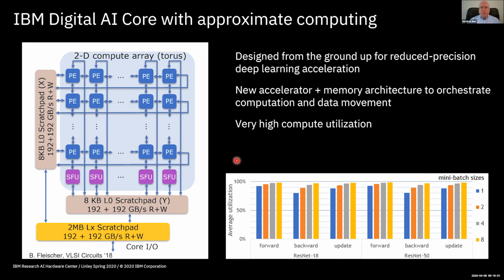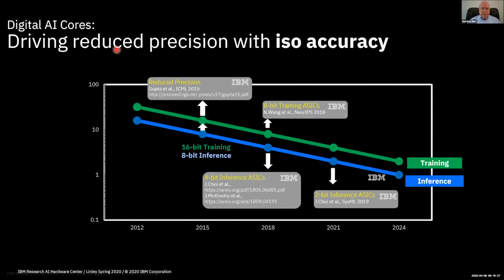It turns out, the approach my colleagues have taken is that by the point you get to 4-bit or 2-bit activations and weights, it actually is more costly to use sparsity unless you could guarantee you're going to be at 90%, 80% sparsity. At only 50% sparsity, it's actually better to just assume you need to operate on every weight and every activation and not put in the extra circuitry to check if there are zeros. So that's the approach that my colleagues have taken.